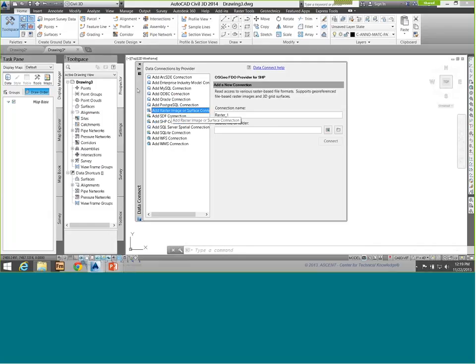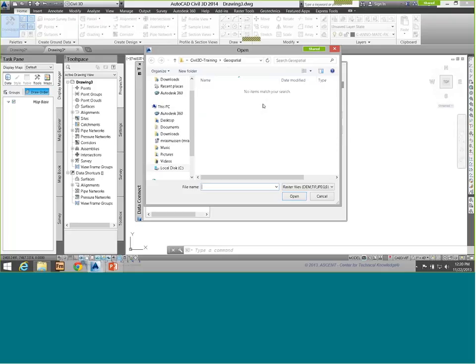as well. So when I'm connecting to data, all I do is select the type of data provider that I have on the left-hand side, and then on the right-hand side, I decide if I want to add one file at a time by clicking the File option, or if I have an entire directory full of images that I want to connect all of those images, I can actually click on the Folder option and just go and browse to the folder that all of those images are in. Of course, they would all need to be in the same place, and you'd want all their world files in the same place as well. I happen to have just one file, so I'm going to go ahead and grab it.